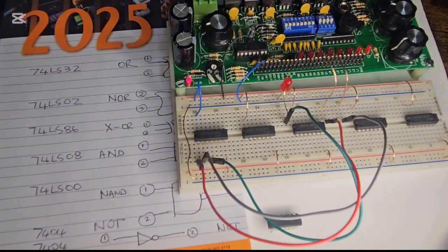There will be situations when you design circuits whereby you want the output to be the opposite of the input. You want something not happening to trigger something. Just a simple example, an alarm. Let's say when my switch is off or when something is off, I want my circuit to warn me. So in that case, you'll use an inversion. Okay, but not dwelling much on the NOT gate, let's move on to the NAND gate.